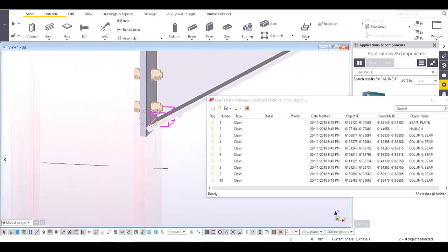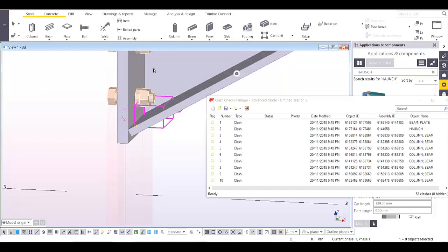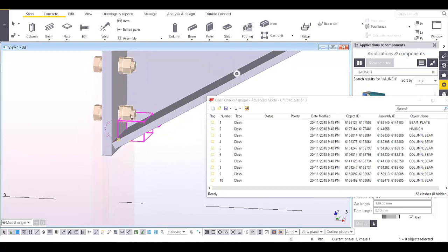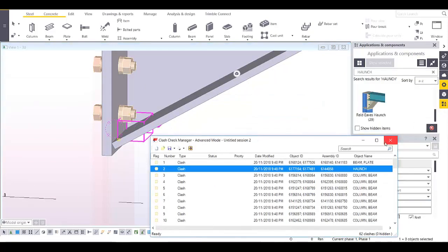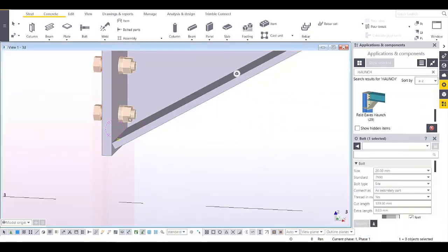All we have to do is to advise the erection people to mirror the bolt. So instead of the head being on the left side, the head will be on the right side. So maybe here, if I double click on the bolt, let me check if we can somehow do the changes here.